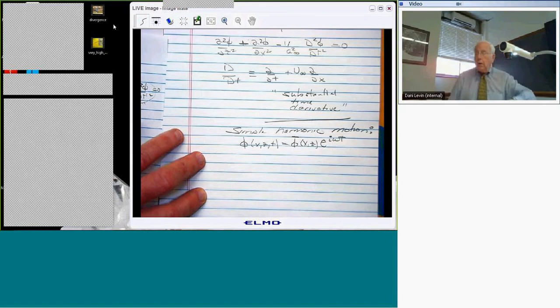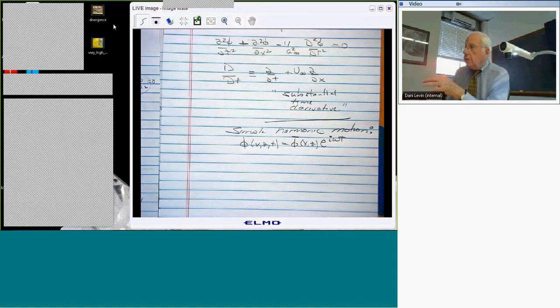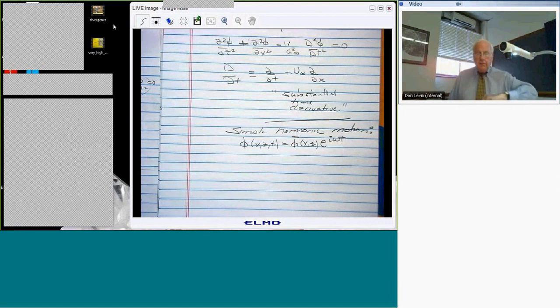We're doing simple harmonic motion because early in the class we said, hey, if I have a linear dynamical system and I can do the simple harmonic motion case, then I can use that to construct the periodic motion case, right, by using a Fourier series. And then I can go from there to a Fourier transform and do the arbitrary time dependence, right? I can get transfer functions. There are aerodynamic transfer functions just like there were structural transfer functions and other aeroelastic transfer functions.